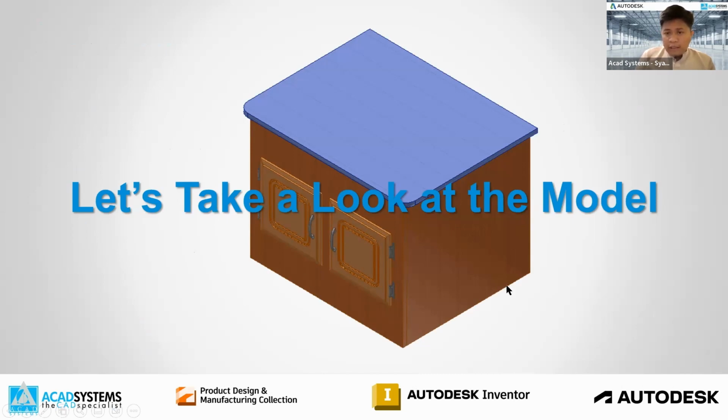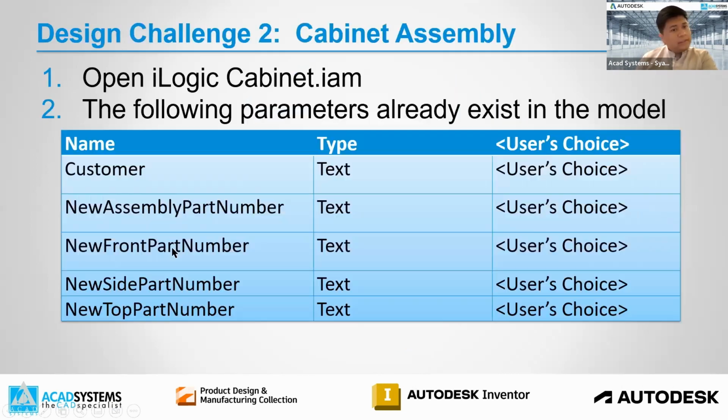So over here, you will see they will have length, width, the height, also the door size, together with the opening. So for this model, the size keeps changing. I don't have a very constant, very simple size. So then what I need to do, first step, open the file, the IAM file, and then directly create a user parameter, just like before.